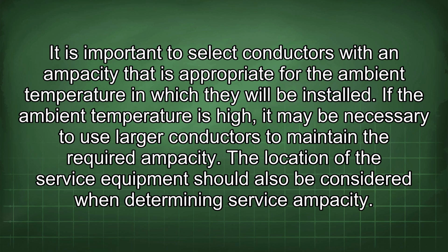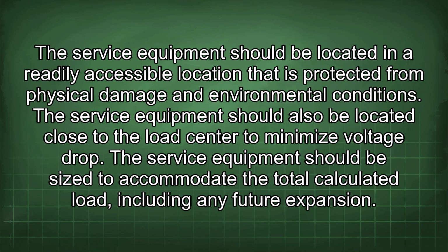ampacity. The location of the service equipment should also be considered when determining service ampacity. Service equipment should be located in a readily accessible location that is protected from physical damage and environmental conditions. The service equipment should also be located close to the load center to minimize voltage drop. The service equipment should be sized to accommodate the total calculated load, including any future expansion.